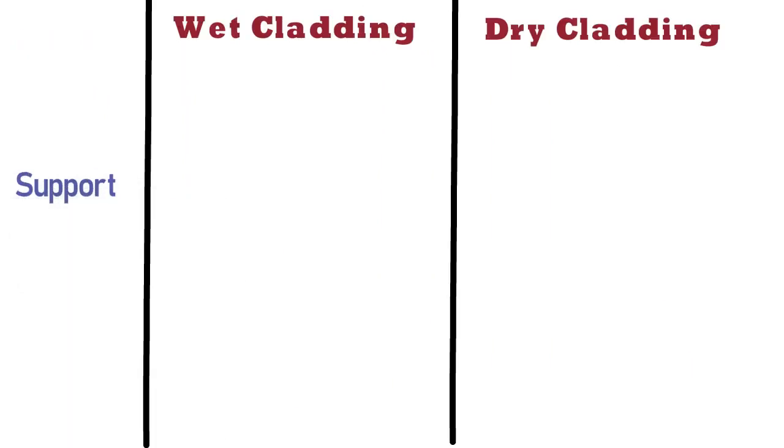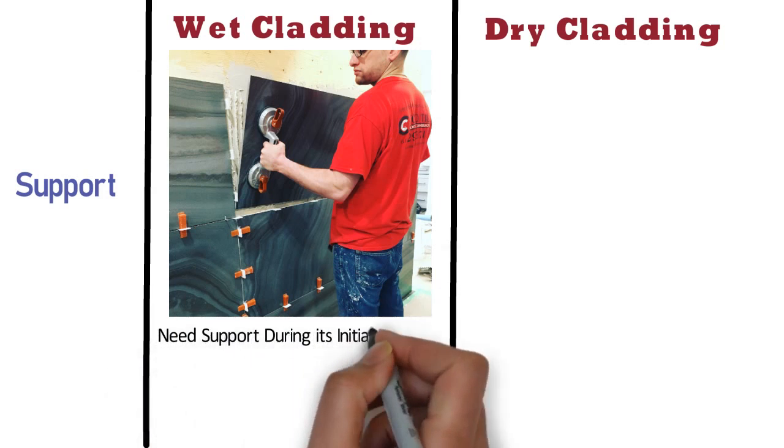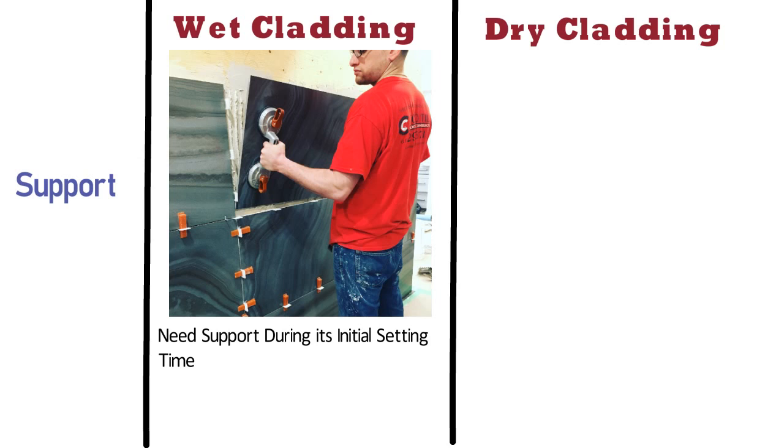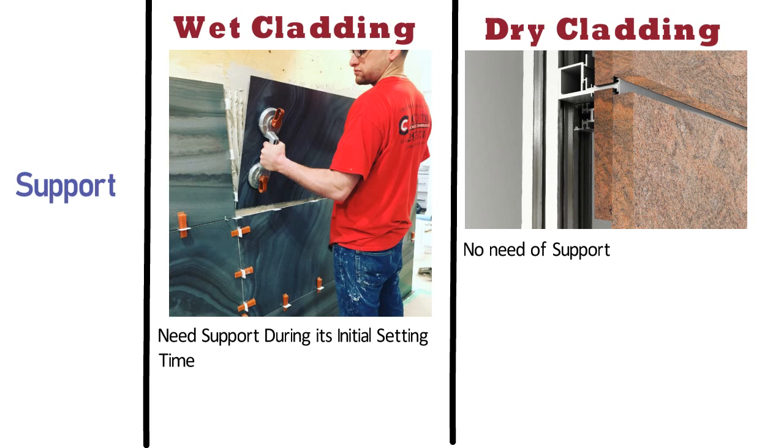Support. In case of wet cladding, proper support to the tile or stone shall be provided during its initial setting time. Whereas in case of dry cladding, there is no need of such kind of support.